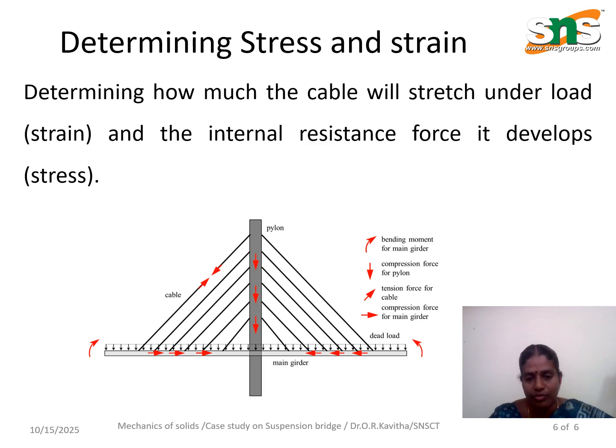This force is nothing but the compressive force. So each and every component is subjected to different loading. Here this is a compressive force and a downward force, and this is also a downward force on the girder, and on two sides a bending moment is created, and the tensile forces are created in the cables. So determining these tensile or compressive stresses and the strains is very important in the design.